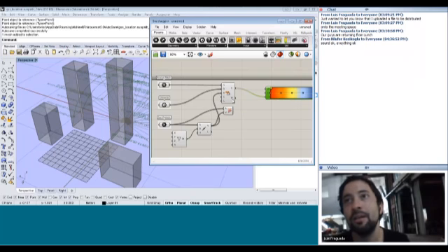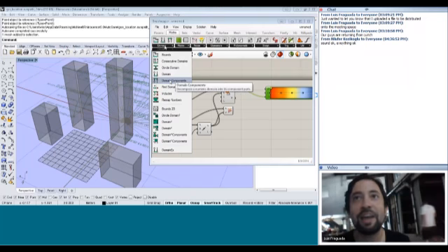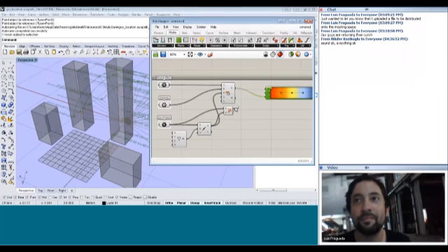So this being a domain, I have to decompose the domain. I'm going to go to Math, Domain, and Domain Components, Decompose a Numeric Domain. It's like deconstructing in the other kinds of things that we've done. I'm going to connect from R to I. And now we have these two numbers out of two separate outputs.